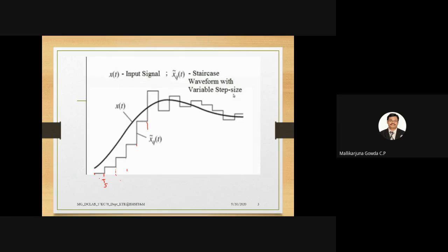Okay, so here at the first TS, at the first sampling duration, it will compare, right? So now the analog signal is greater than the approximated version of the signal, right? So now what happens? The output of the comparator will be positive. So it will be incremented by delta. Okay, so it reaches this point, right? And it remains in that same duration. Okay, then at 2TS,